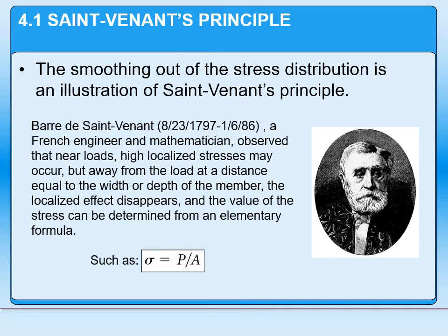It turns out that this original concept was first noticed by a French engineer and mathematician named Barré de Saint-Venant, and pardon my French if I've mispronounced that. He observed that when we look at loads, there's going to be a high localized stress where they're applied, but as you get further away, the stress is going to drop off and we're going to have a more uniform distribution.